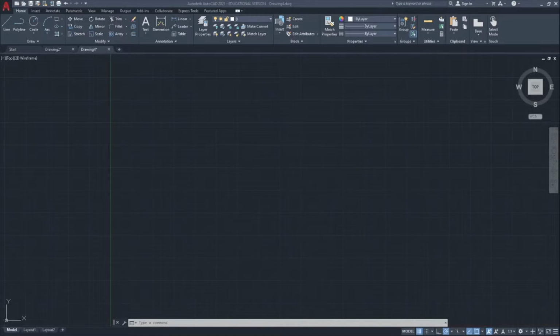In this video, I'm going to go through how to open up your 3D toolbars that you're going to use when it comes time to 3D model in AutoCAD. So these toolbars are not easily just found in the ribbon in our acad.dwg drawing. So what we're going to do instead is type in the subtract symbol and type in toolbar.